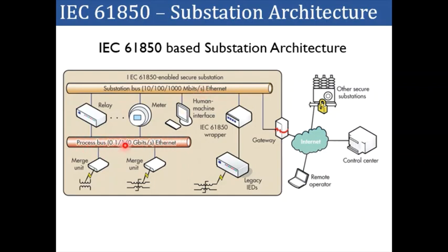Because one is mainly required for the data acquisition, that is called process bus. So the process bus will be responsible to share the measurement data to the various devices connected in the substation. Here the merging unit plays an important role, where the merging unit will club the voltage and current measurements and convert them into digital format, and only one data stream is required to be communicated to the process bus.